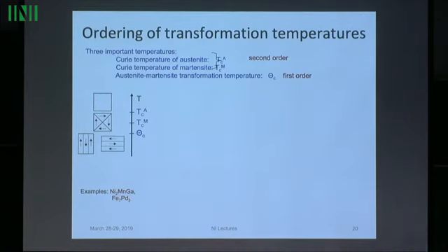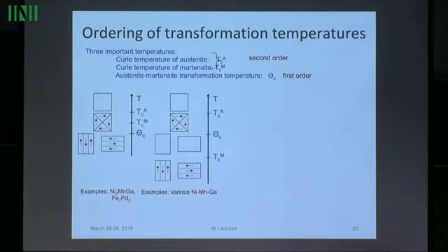Typically, the length of the magnetization is the main vector field you're interested in in that case, and it could also jump. I didn't really draw it there, but it could change abruptly at the phase transformation. Typically it does. You could also have this situation: austenite ferromagnetically orders, then transforms to martensite that is non-ferromagnetic, and then later, because this has very different lattice parameters from this, it could decide to ferromagnetically order at a lower temperature.